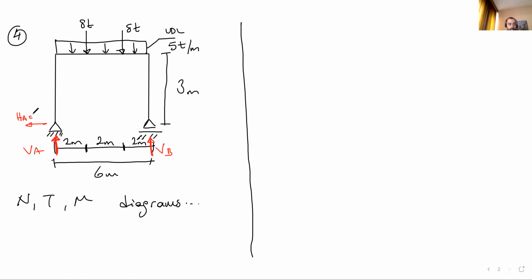But you know, write the total X, total Y, or total MA equals 0, total MB equals 0. Okay. You can write these equations. Now, HA is 4 here, vertical A here, 21 ton, vertical B here, 25 tons. Okay. Now, we have all the loadings on our structural system.